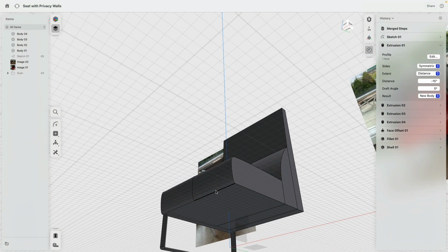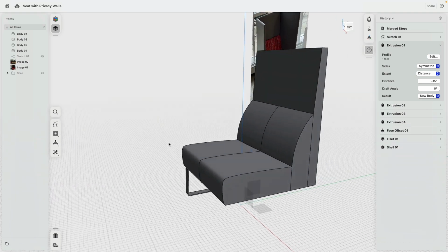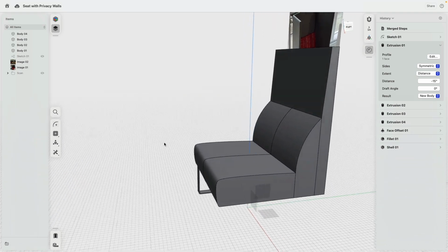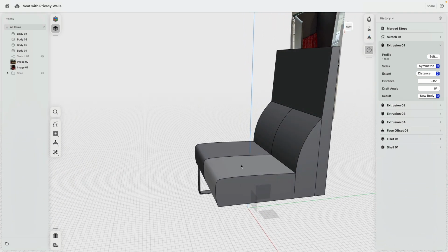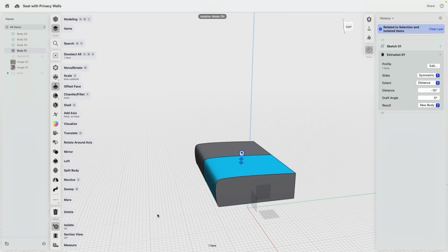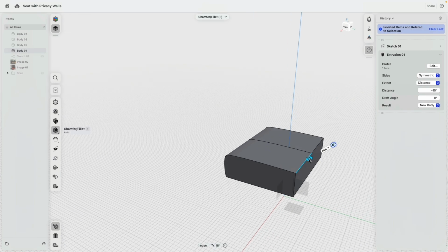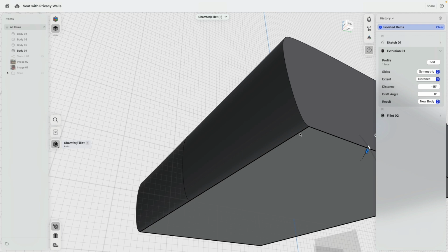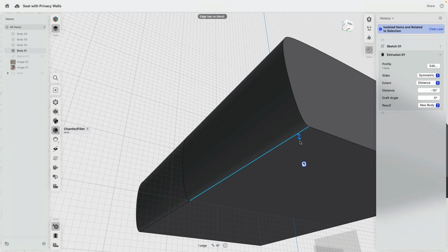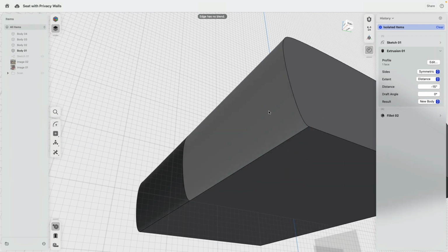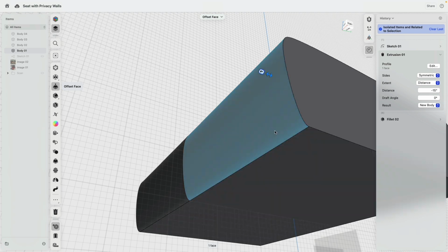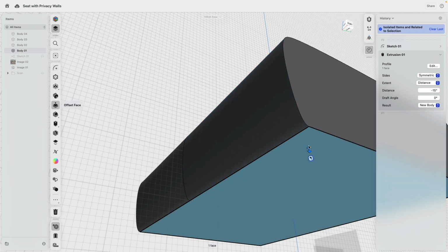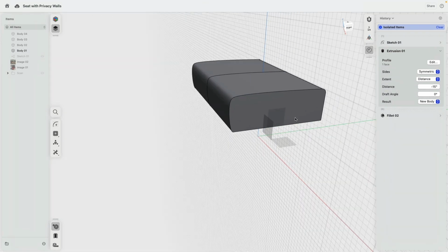This corner and the one down here, we nearly have pre-rounded already. So now we can go ahead and start rounding individual elements. So I go ahead and say, good, this one, just round a little bit. Let's say like this. The one edge down here, we don't really see, so we don't need to round this. This edge we can't really round because this surface already flows smoothly into that surface.